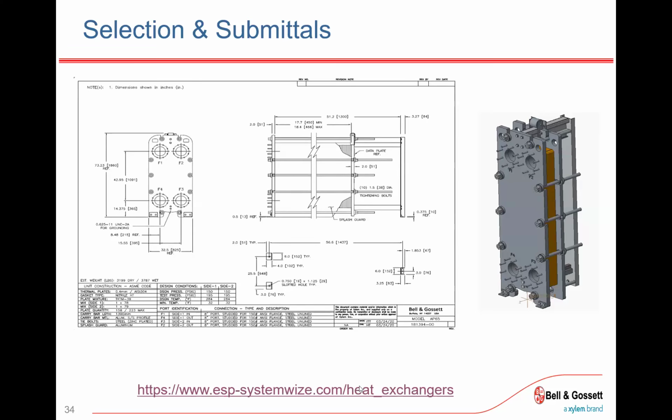So the next one, you'd be able to click, you'd say, do I want to have stainless lined ports, or do I want to have flanged ports? If we didn't have NSF selected, there'd be a bunch more options. It's where you'd add your insulation blanket and so on. But ultimately, I just want to show that you can get your 3D file. You hit save. From there, you'll get your item that you can import into Revit.